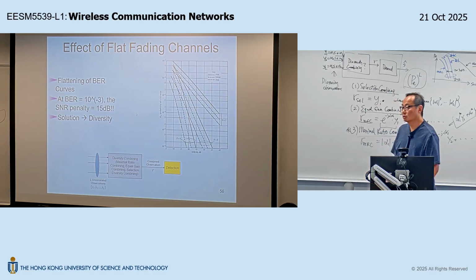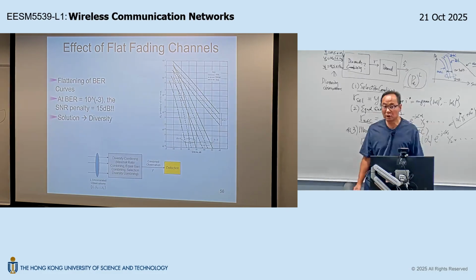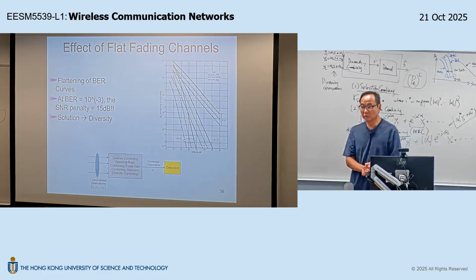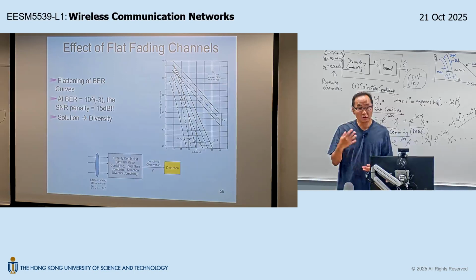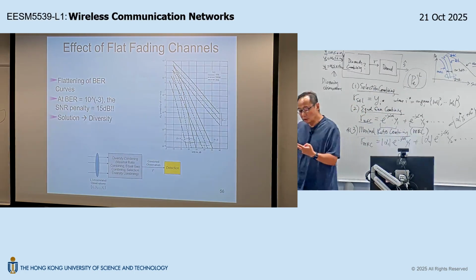Okay. So this is the 1-star trouble. Once again, the 1-star trouble is the error probability curve falling off slowly. And whenever you hit this 1-star trouble, always think about diversity. Diversity is your solution roadmap. The question is, how can you generate diversity observations? It can be from time, frequency, and space.